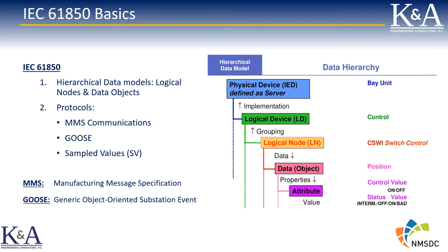So that's the primary defining characteristic of IEC 61850. The other defining characteristics are the protocols that it is mapped to currently. Those protocols consist of MMS communications. Those are data messages that are sent from the devices within the substation to the data concentrator or gateway to update values at the level of the SCADA information, let's say, for visualization by the station operator on his HMI screen.